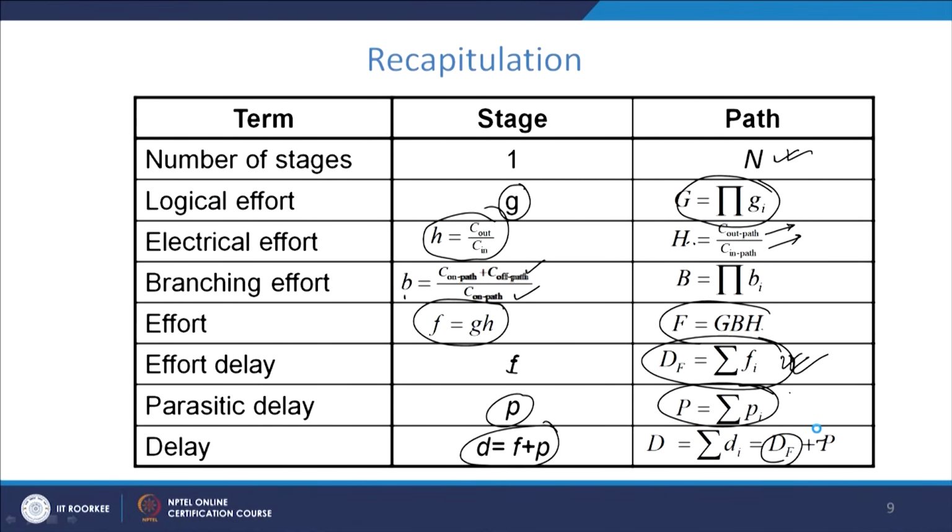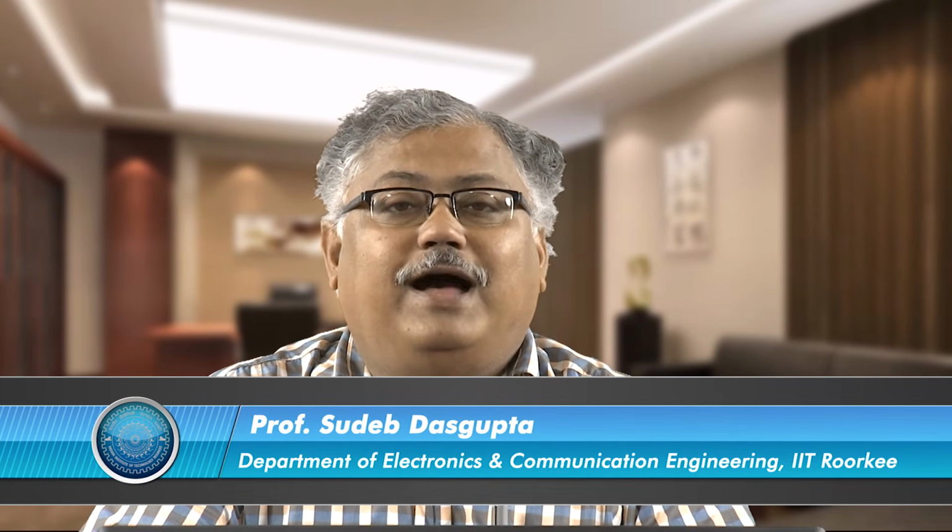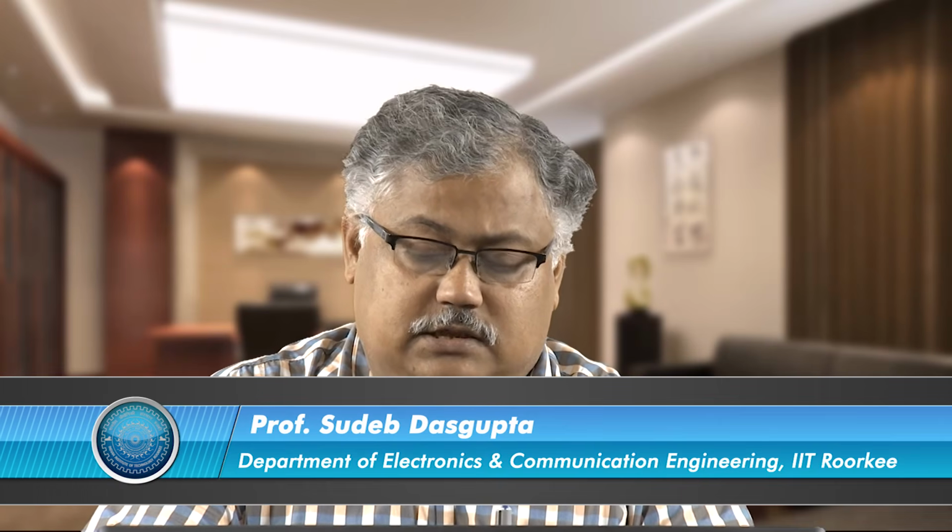Today in this module we learned how to calculate the value of logical effort, so given any gate, you should be able to calculate its logical effort. From logical effort, given the load capacitances, you can calculate the path effort. Once path effort is known, you already know the parasitic value of a particular gate, and therefore you can calculate the total delay, which equals f plus p. This gives you a brief idea about how you are able to achieve a relatively low value of path delay in this design, and this is the whole motivation for doing this chapter on delay.